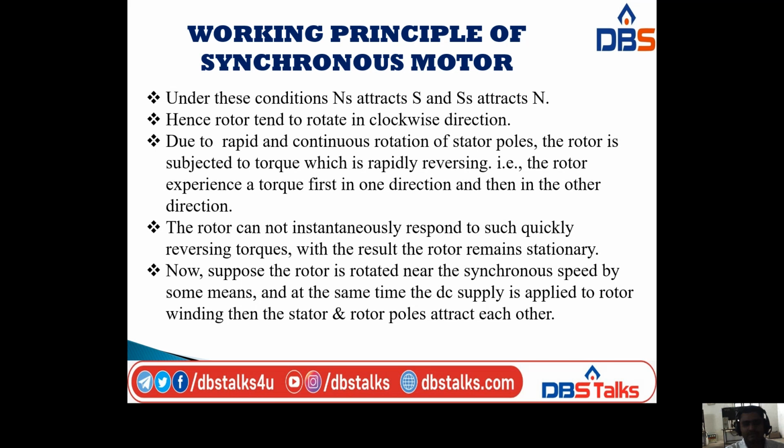Under these conditions, after interchanging the positions, N_S, the stator pole, attracts S, the rotor pole, and S_S, the stator pole, attracts N, the rotor pole. So under these conditions N_S attracts S and S_S attracts N. Hence the rotor tends to rotate in the clockwise direction. In the previous half period, the rotor tended to rotate in the anti-clockwise direction.